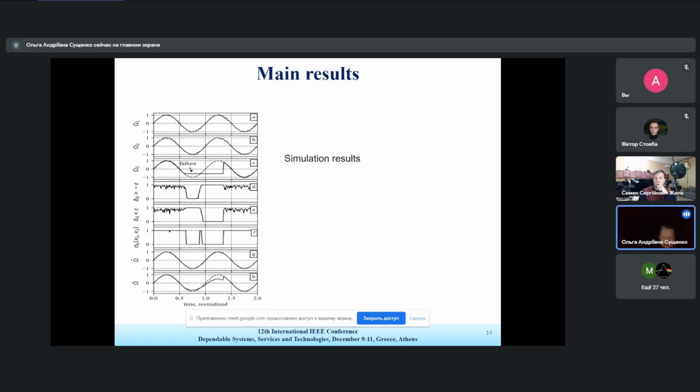Figures A, B, C represent the input signals in the form of normalized signals, which enter separate triaxial measuring units based on MEMS rate gyroscopes. To ensure correspondence of the measuring process to operating conditions, sensor outputs are supplemented with a random noise of definite amplitude. To check the algorithm, it's necessary to assume that one of the sensors has failed for some time.